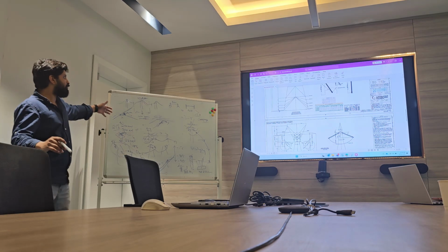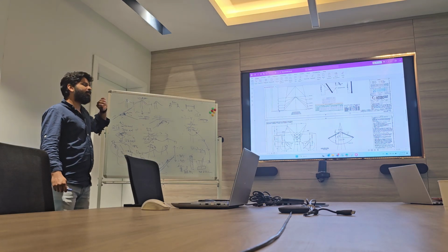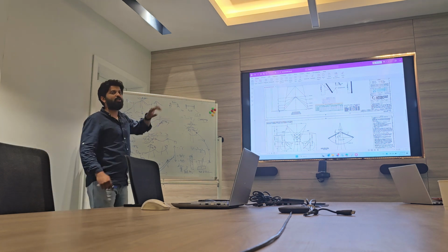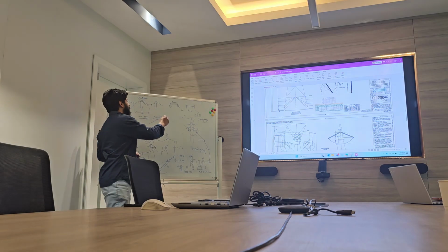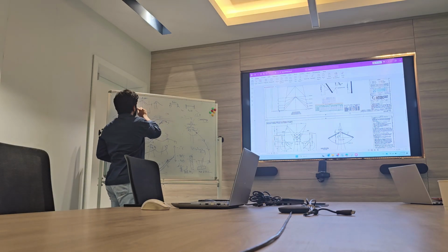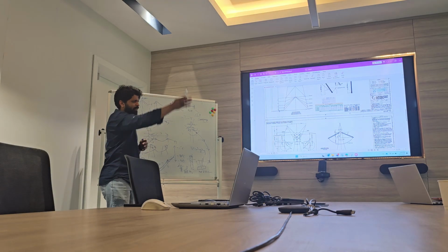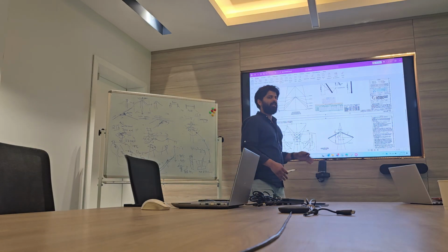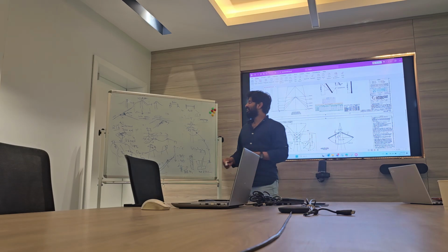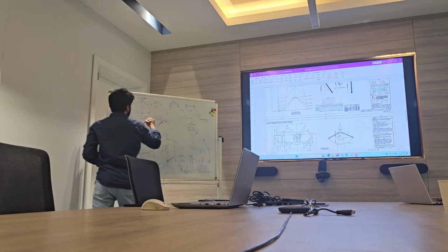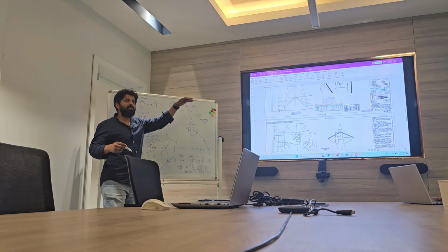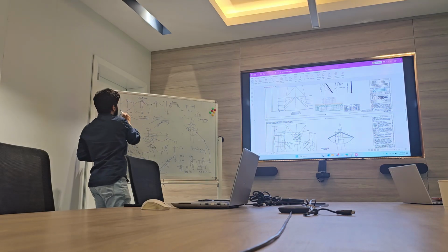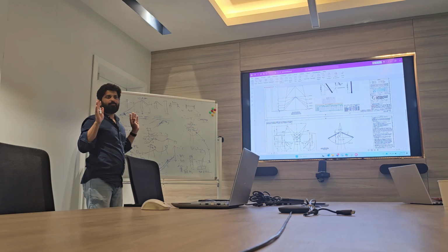But you introduce, say for example now, a section tower, a dead end tower, to be installed at every 12 kilometers. That means I have a span of 12 kilometers of suspension towers, straight line. After 12 kilometers, I have to put a dead end tower here, a dead end tower here. This is called an anti-cascade tower. It means if this wire breaks, all the suspension towers will fail unless it reaches the dead end tower. It will stop.